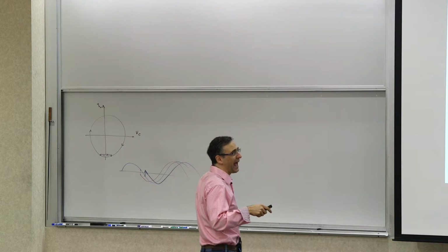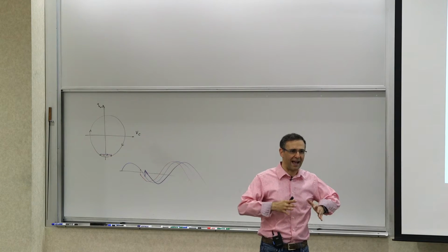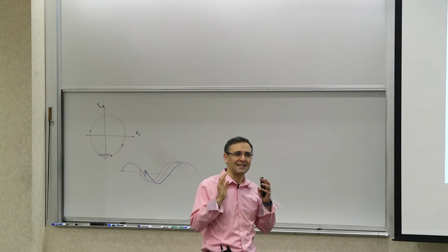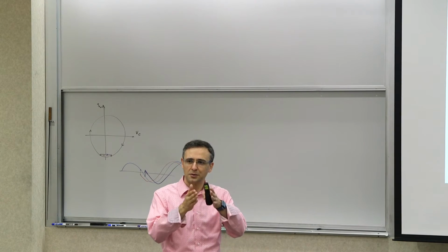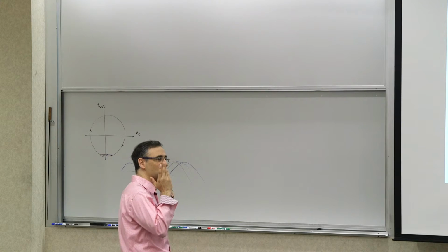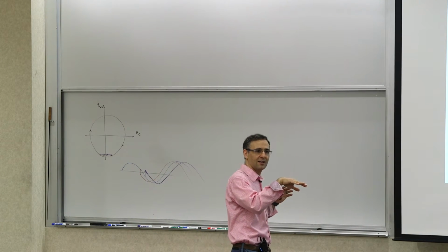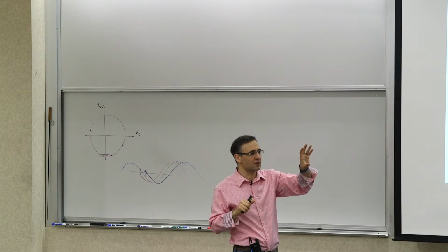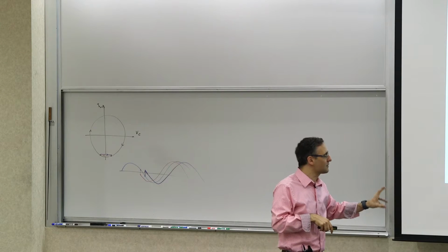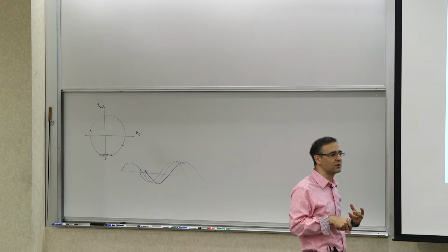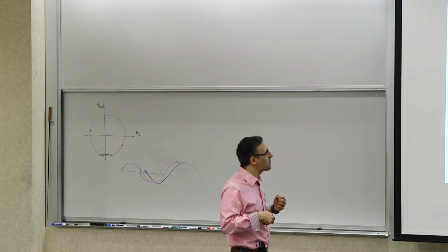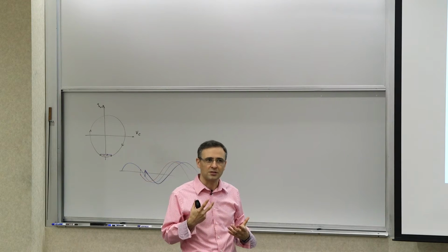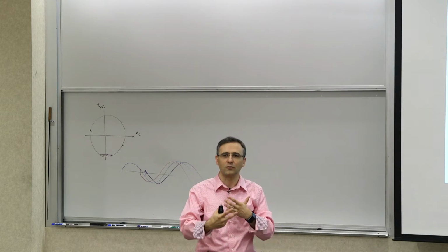The first path is a filter around DC that passes stuff around low frequency. The second is a filter that passes stuff around the frequency of oscillation. The third path passes stuff around the second harmonic. So each one of them captures stuff around one of the integer multiples of the oscillation frequency, goes through an ideal integration, and then adds them all up to produce the total phase. So this is probably a better picture to show the evolution of noise inside an oscillator.